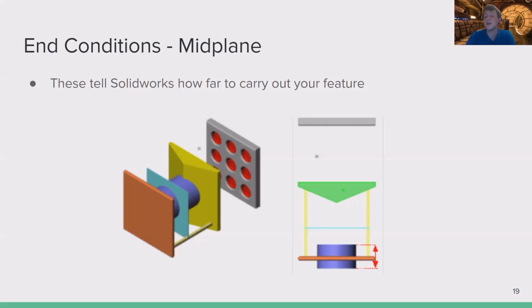One of the main use cases that we really like this for is when you first start out on a part, you'll get 3 orthogonal planes. So you have right, top, and front. And you'll usually begin a sketch, and let's say you put your geometry right in the middle of those 2 planes that you're sketching on. When you make this a 3-dimensional feature, and usually your first feature is like the big meat of your part, if you're thinking about it.